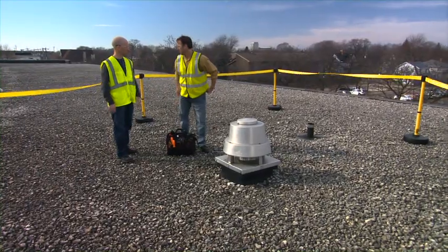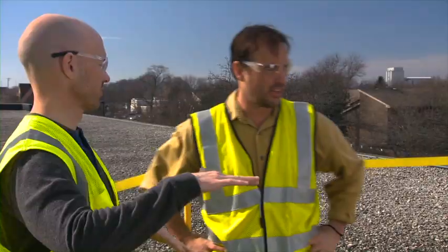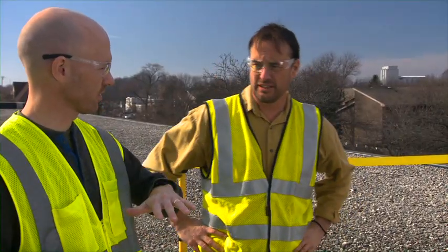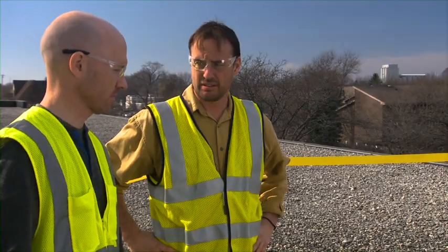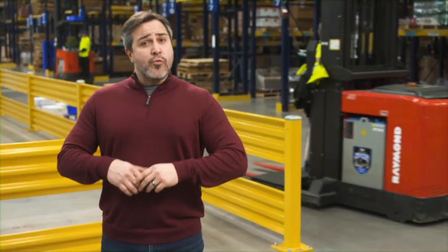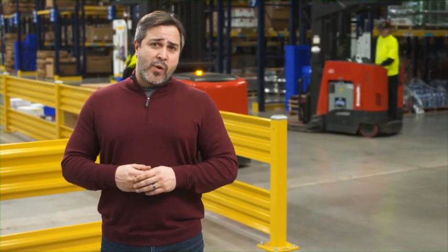This type of fall protection is provided via a warning line that defines a portion of the roof in which you are allowed to work without additional fall protection. The line warns you about the fall hazard at the roof edge. If your employer was unable to eliminate or protect against fall hazards through modifications to the work environment, they are required to determine the most appropriate form of personal protective equipment, or PPE, you'll need to use.